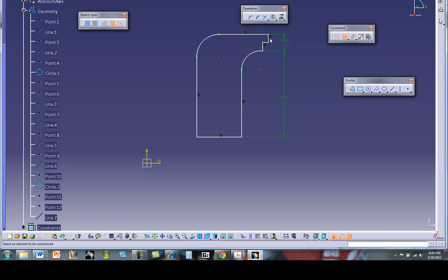I'm going to change my geometry a little bit because I got it just backwards. Just drag that in a little bit to make it conform to the same shape. So now I'm going to go then from this line here up to that line up here. And again, if I drag these things out and try to line them up, it's just easier for a later time when you refer back to them. Okay, so I'm trying to put in all my base features from bottom towards top.